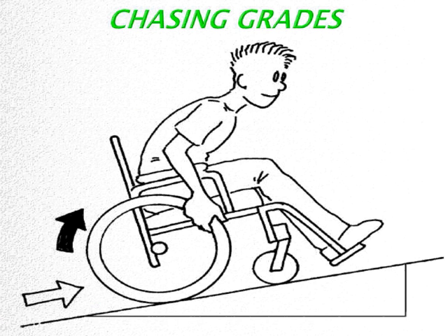Now, chasing grades, we talked about the running slope being a maximum of 8.33%. Now, what do you do if the natural terrain, the road grade and the sidewalk grade itself is pretty steep? It's 8.3 or something even steeper, and now you're asking me to put in an 8.33% ramp, and you may have to chase that to the next county to meet the existing grade.